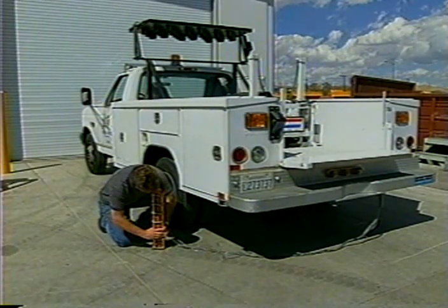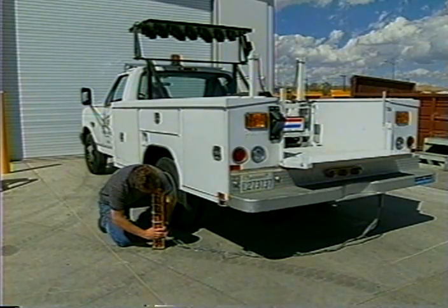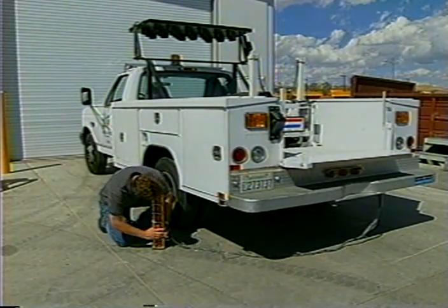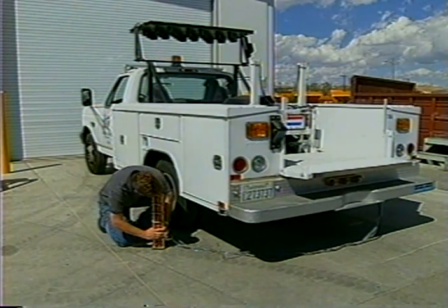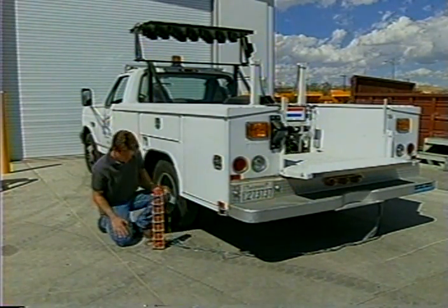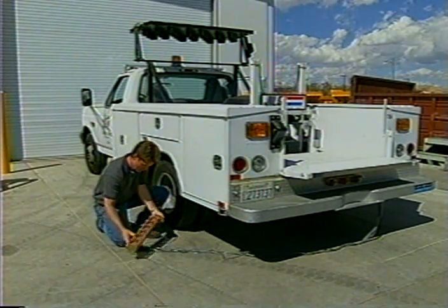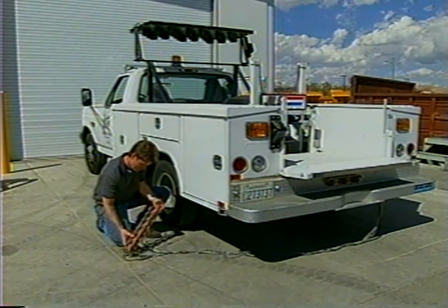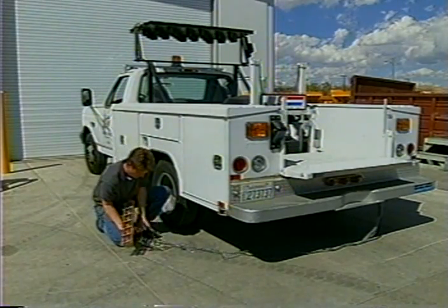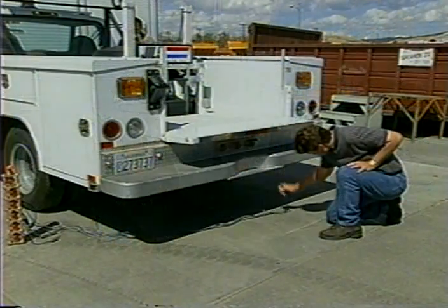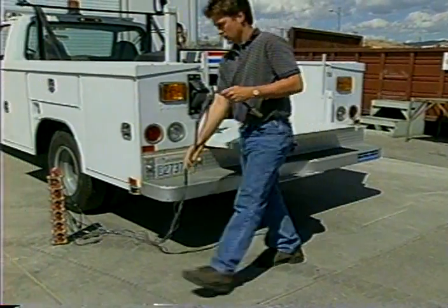Because relative calibration requires no special equipment besides the test stand, you can do it at your home garage or anywhere else, and you should do it often. It allows you to catch problems and avoid gathering days, weeks, or months of bad data. That's why your agency should establish a policy of doing this relative calibration regularly on all FWDs. LTPP's policy is to do it monthly. When you complete the relative calibration, you're done.